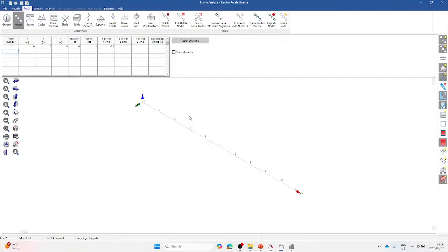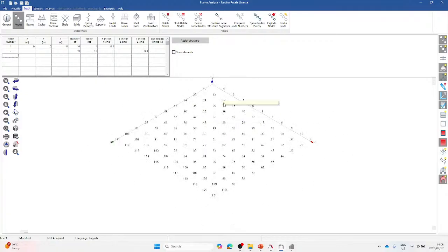And then from there, to actually define my slab, I will create extra rows in the Z direction, and I will use the block copy function. So, and let's have 10 extra rows. And the last node was node 11, so the next node will definitely be node 12. So the node increment should be 11 for the next node at this point. And then, like I said, I will space them 0.3 in the Z direction. And just like that, we have defined the first set of coordinates for our model.